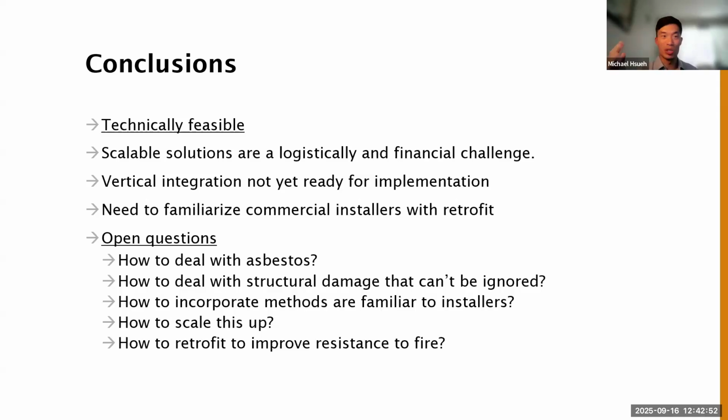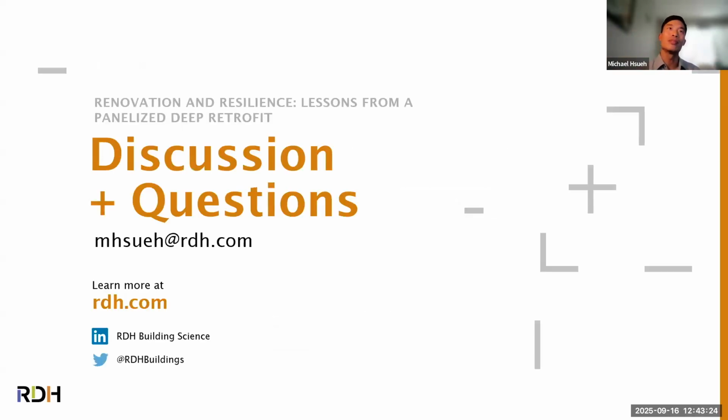The roofing that we installed was Class A roofing, has less combustibility. Same with the wall panels that we installed. These are things that we were focused on. We did it from the perspective of energy efficiency and thermal comfort and things like that. But it wasn't a trade-off that we had to do for hardening these homes against fire. It kind of enhanced their value beyond that as well. So something to consider and maybe incorporate further into any further retrofits that we're doing.